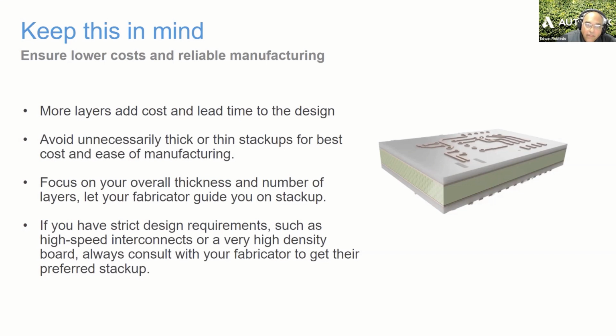I would just like to pitch in here that many board houses or fabricators actually offer a DRC setting, which is compatible with Fusion 360. Therefore, you could actually load them, and they have them for different layer stack ups. So they'll have a 2 layer stack up or a 16 layer stack up DRC, which you could actually load. That way, you're doing your best to follow the criteria that work best for them. Yeah, and if you see that they're listed as Eagle, they'll work in Fusion 360 Electronics as well. Yes, and in fact, we have a number of DRC files for Eagle on our GitHub repo.